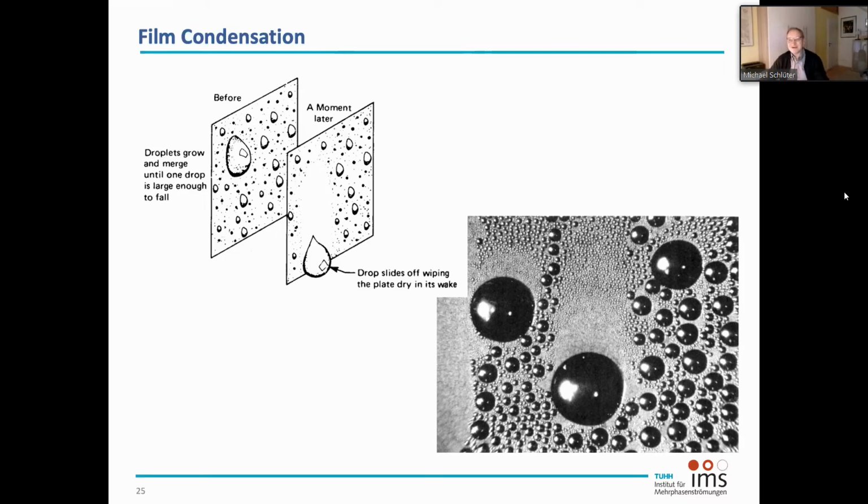And even here you have a very good heat transfer performance because here you get the latent heat back by the condensation process. And if we have an increased convection for evaporation, if the vapor bubbles are rising, here you have an additional convection by the droplets who are created and who are running down the vertical surface.